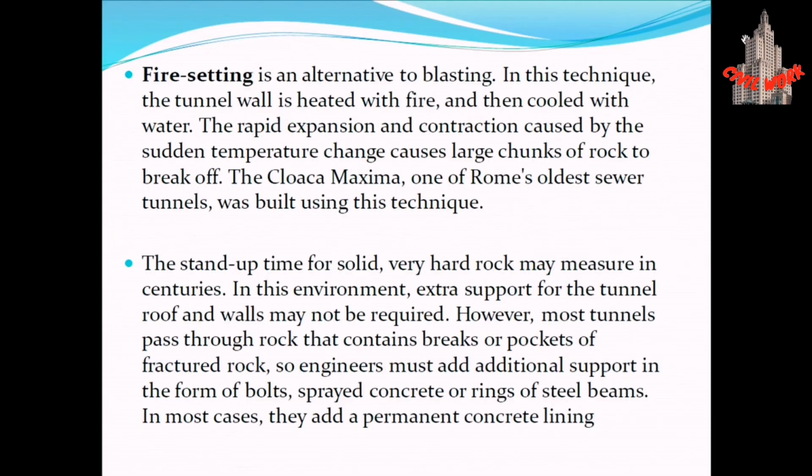Now the second method for the excavation of a tunnel in rocky strata is fire setting. Fire setting is an alternative to blasting. In this technique, the tunnel wall is heated with fire and then cooled with water. The rapid expansion and contraction caused by the sudden temperature change causes large chunks of rock to break off. The Cloaca Maxima, one of Rome's oldest sewer tunnels, was built using this technique.